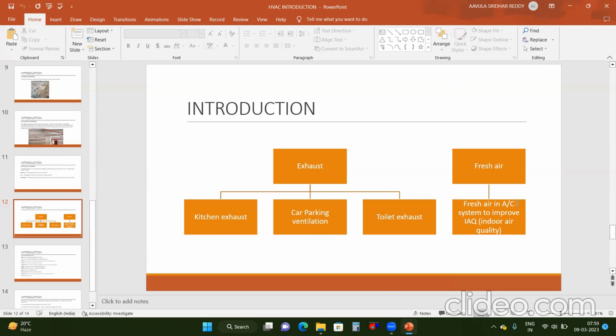We'll generally take some fresh air from the outside. We'll know how much fresh air we need to take for each and every room in the designing part. That amount of air we will take from the outside atmosphere and connect to our unit. So by this, a certain 10% of air will be continuously taken from the atmosphere, so that the indoor air quality will be maintained, humans also feel comfort, and that is good for health. Okay. So we have ASHRAE requirements for the fresh air. When we go into heat load calculation, we will see what the fresh air requirement is in every application.